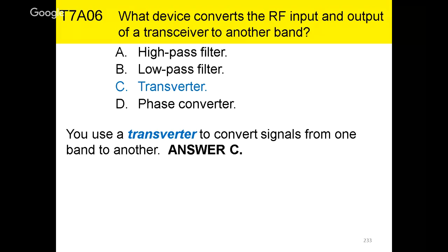Some of the HF rigs that I was talking about earlier, if you wanted to operate 2-meter sideband, let's say, you could put a 2-meter transverter or even a 6-meter transverter. There were hookups on some radios where you could put a transverter on and actually convert that to a 2-meter or 6-meter signal for that particular band. And that's what a transverter does.